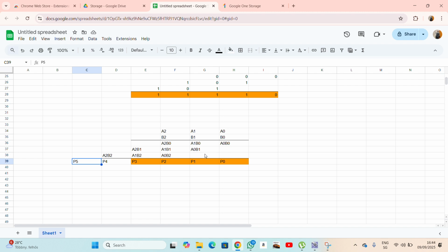So this is going to be added to nothing, but here we're going to add 2 of them. Because we're adding only 2 variables, in this case A1, B0 and A0, B1, it means you're going to need a half adder at this point. Then here, the carry out of this column is going to be added to these first 2, and that's why at this point we're going to need a full adder, and then later on that's going to be added to the final one, which is a half adder.